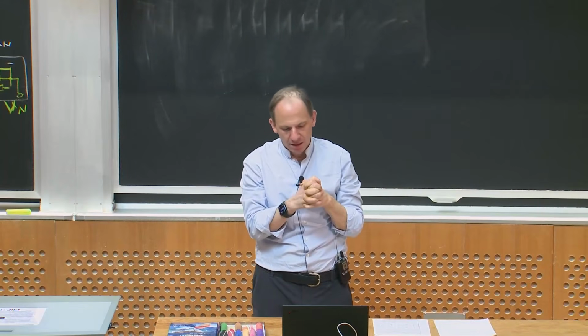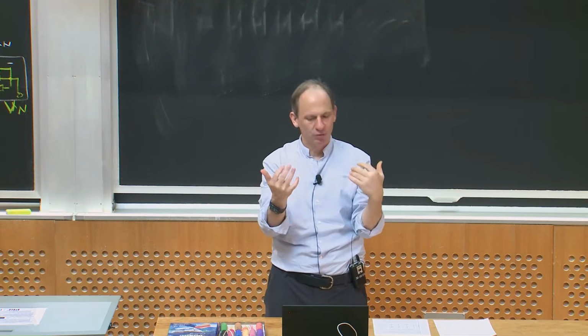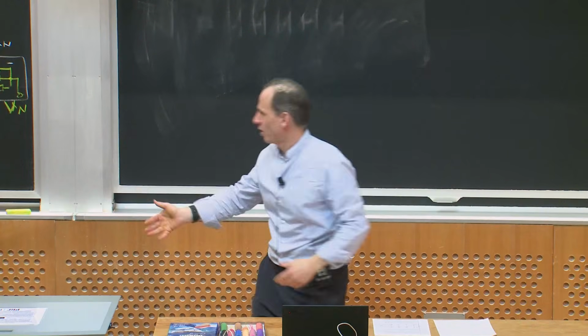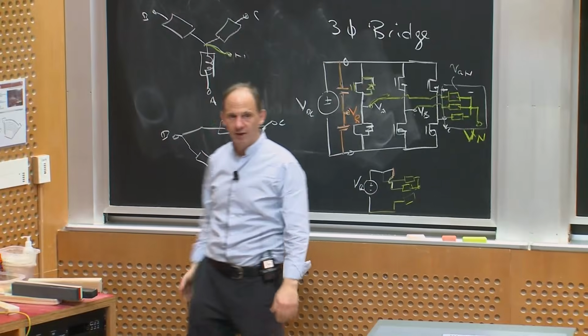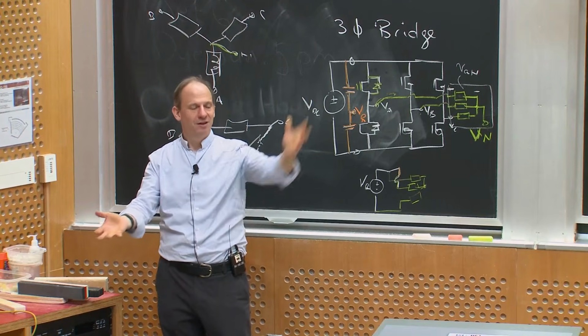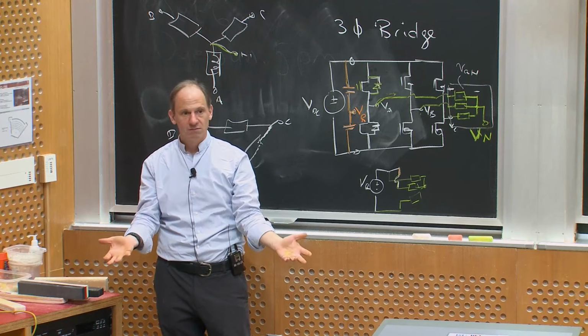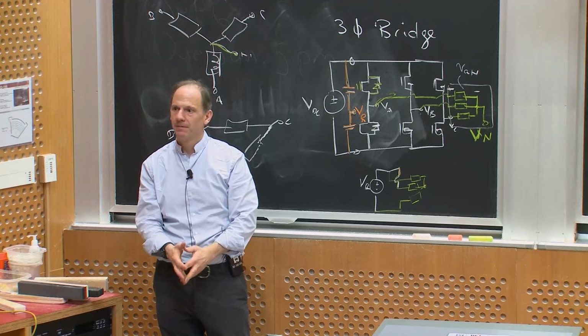Now, if I do that, the line-to-reference voltages, these square waves, have third harmonic, right? But because I'm taking the difference between 2 of them to get the line-to-line voltage, shifted by 1/3 of a cycle, all the triple N components disappear. So the line-to-line voltages have no triple N components. Right? So whatever my motor sees, it's line to line. If I'm driving, say, a delta connected machine, it will see no triple N drive. And that's just free because I have this 3-phase inverter structure. If everything's balanced, it can't generate triple N line to line. Any questions about that?